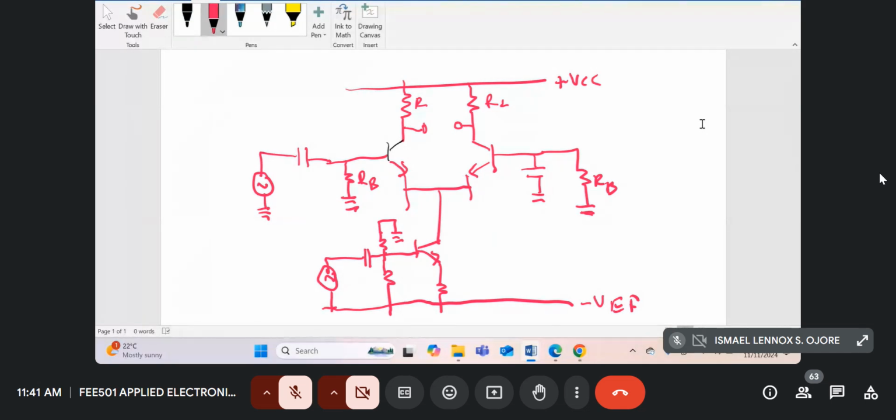So anyway, when you're designing with a small signal transistor, normally you pick the collector currents to be approximately 1 milliamp when there's no signal. 1 milliamp or 2 milliamps, 1 to 2 milliamps. If you want more gain, you use 2 milliamps. But we can use 1 milliamp. So 1 milliamp will flow over here, 1 milliamp will flow over here when there's no signal. So here you need 2 milliamps. So you go to bias, say that you got 2 milliamps over here.